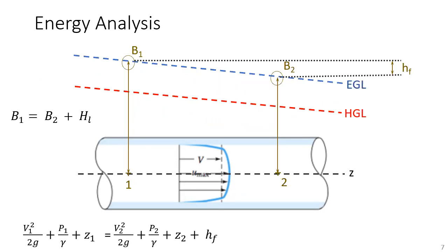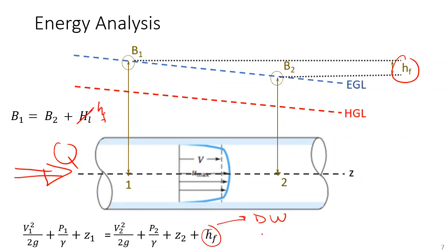We have discharge flowing in a pipe. That, of course, is generating friction losses. And when our energy losses are only friction losses, for the friction loss equation, we can either use Darcy-Weisbach or we can use Hazen-Williams. Again, you will not get the same answer if you use both equations. So you should be aware of that.